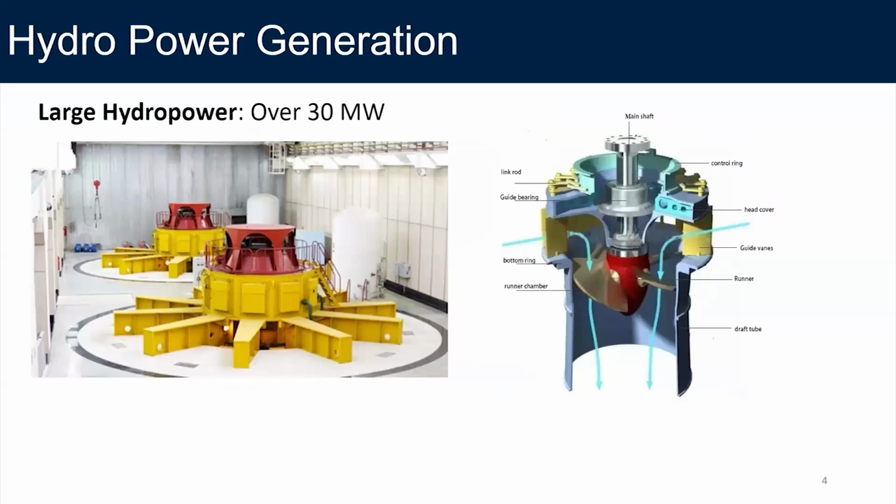So the other application is hydropower. Obviously, the large hydropower stations use synchronous generators, and they tend to be without any gearbox because we don't have the need to reduce weight, and you eliminate the gearbox requirement altogether. So in large hydropower, it's naturally beneficial to have direct drive synchronous generators running. That's one application that we find in Sri Lanka most often.